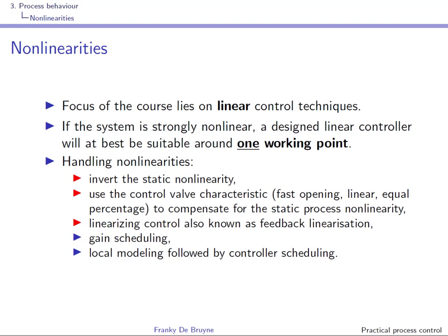One technique that is also left for your information is so-called linearizing or feedback linearization control. The idea is to use a controller, a nonlinear controller, to transform the nonlinear system into an equivalent linear system. Once you have this equivalent linear system, you can use standard linear techniques to design a controller on top of the linearizing controller.